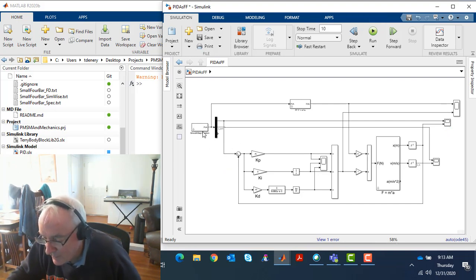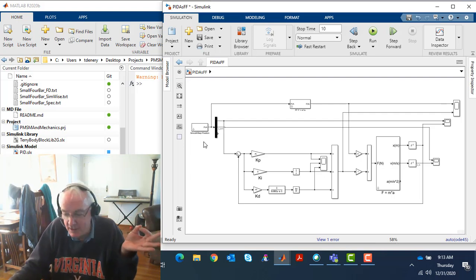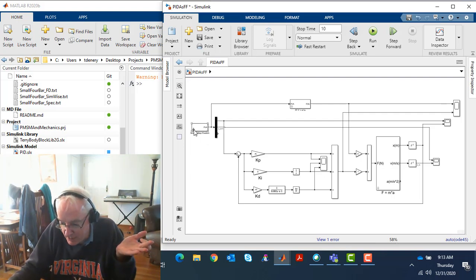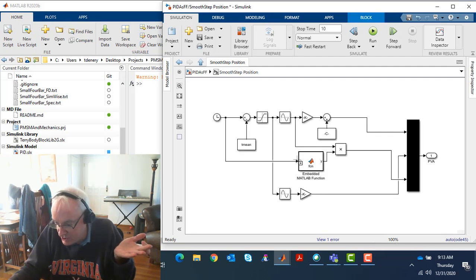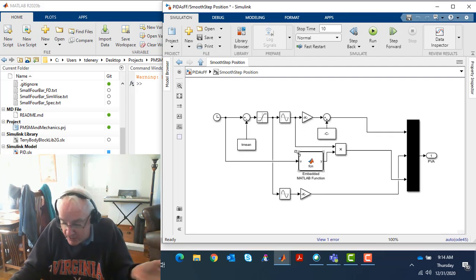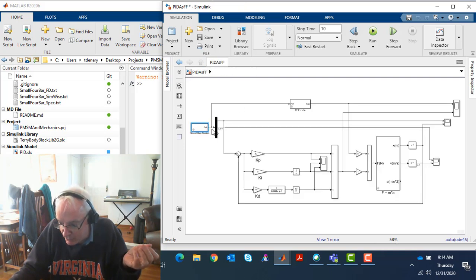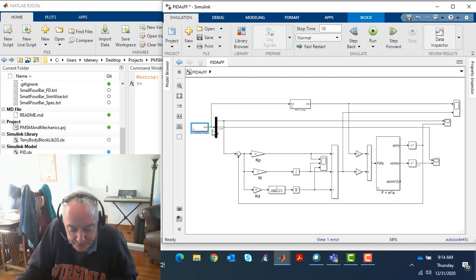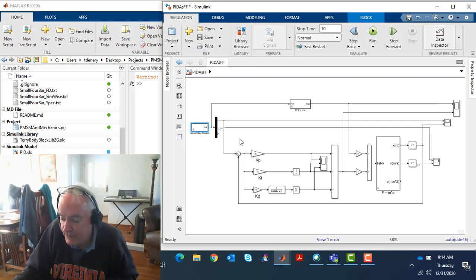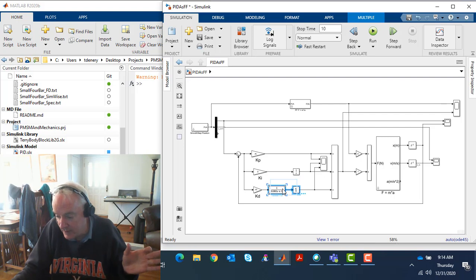and I'm going to say that the way I was doing it before, there's a real benefit in the purity of the calculation, that I'm not applying a numerical integrator or differentiation here. I am formulaically assessing individually all three: position, velocity, and acceleration. I'm using that. And therefore, I have a much better evaluation of the derivative when I measure it from my own velocity as opposed to allowing this combination of transfer function and du/dt block to do it for me. Okay, and so I'll say that's the difference, and that's why this one goes unstable, right?